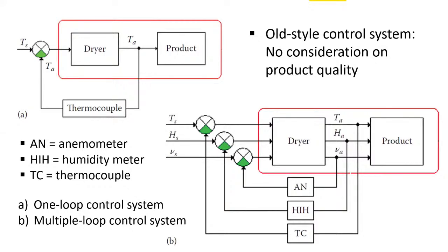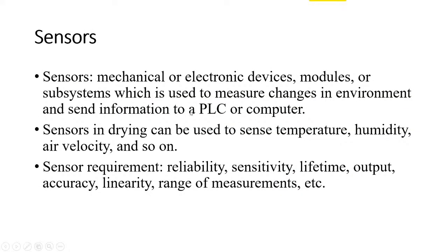But probably the smarter way is to monitor the color of the rough rice during the processing. We can adjust the temperature based on the drying period. Probably we can apply a little bit lower temperature after the critical moisture content is achieved. This is in order to minimize the breakage of the grain during the drying operation. And of course, we need some sensors.